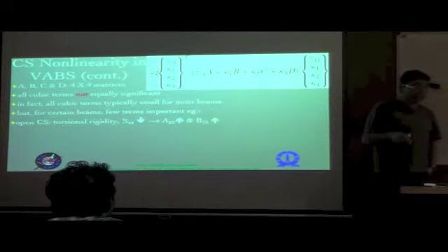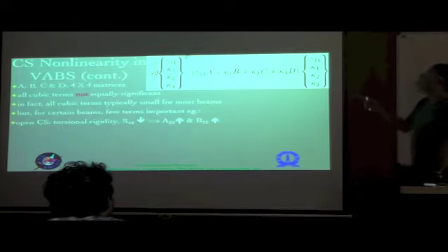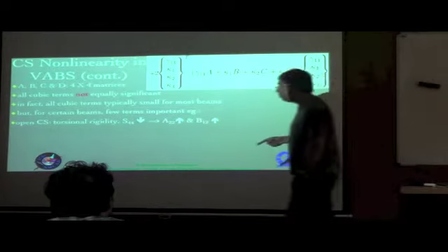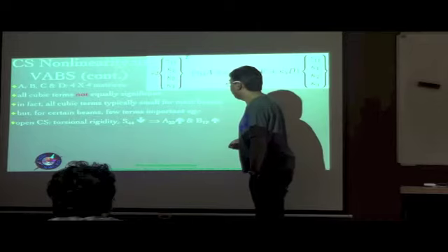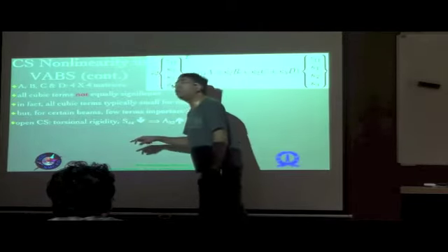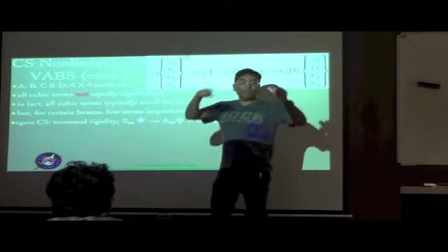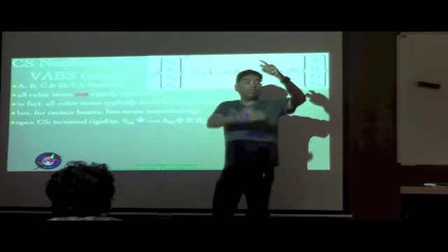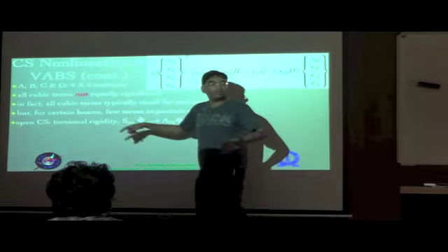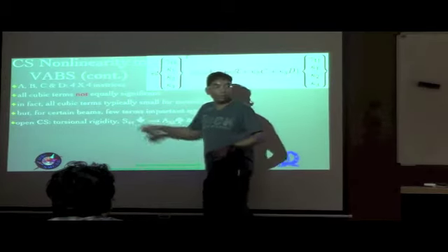Remember that in the 4x4 classical matrix that we have, this S44, sorry, I think it should be S22 if it's in the classical matrix, but I think this is for the one with the transverse shear, where you have gamma 1,1, gamma 1,2, gamma 1,3, and then kappa 1. So the kappa 1 is the fourth in the order, and therefore you're talking about S44 there. Whereas if it were the barred quantities, you would be talking about S bar 22.